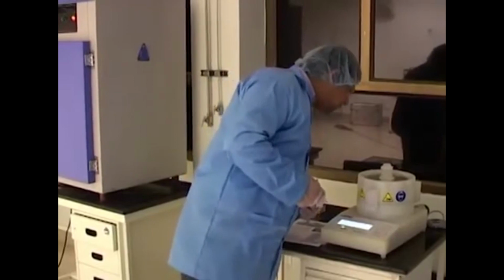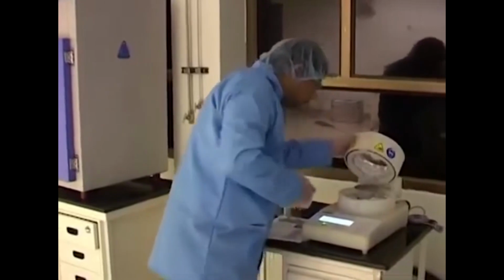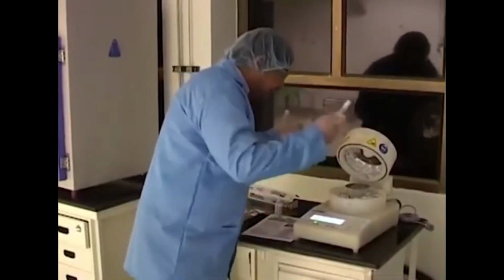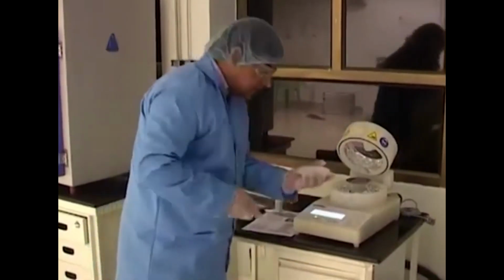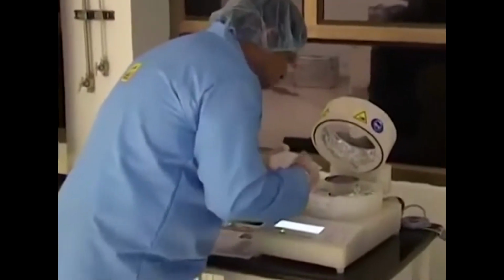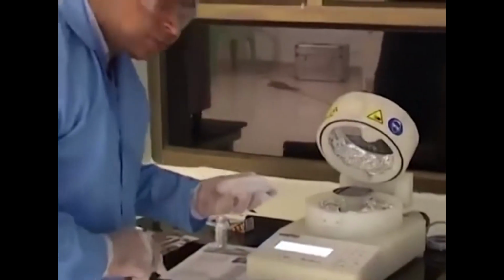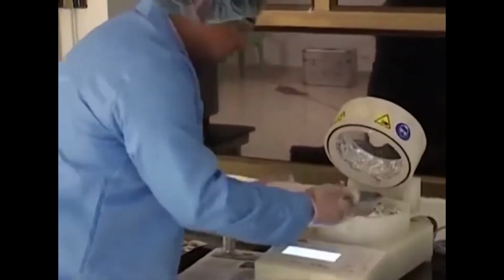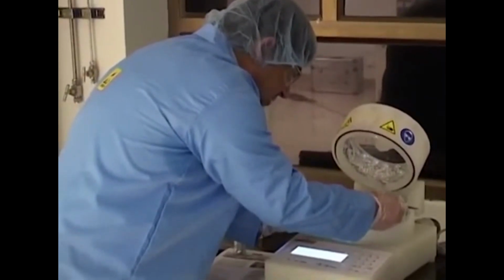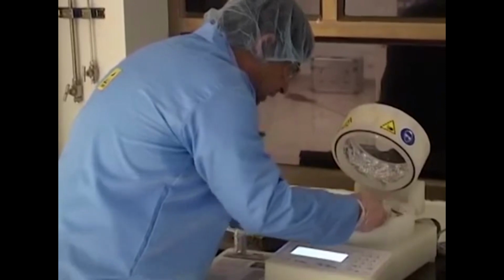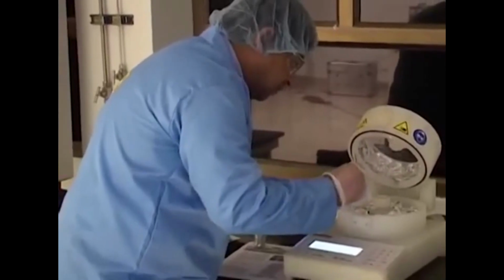So essentially now the program has stopped, and I am going to slowly pull, and as you can see here, there is a thin film of resist on the top of the surface. I am going to take the wafer box here. So the first thing we need to do is to close the vacuum so that we can decouple the wafer from the spin table. We take a very small portion with this tweezer, and then slowly transfer the resist coated surface onto this wafer holding box.